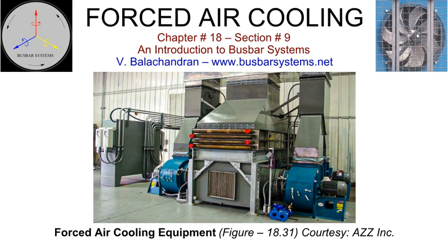Since the isolated phase bus will be designed for a maximum ambient temperature for its natural air-cooled rating, air from the surrounding area can be used at the inlet. Most isolated phase bus with forced air cooling use a closed-loop system wherein the air from the IPB outlet is recirculated through a heat exchanger to the inlet of a cooling system. In such a case, an air-to-water heat exchanger is usually incorporated as it is the most compact, efficient, and economical device. The power requirement for the forced cooling system is added to the losses in the isolated phase bus for capitalization.